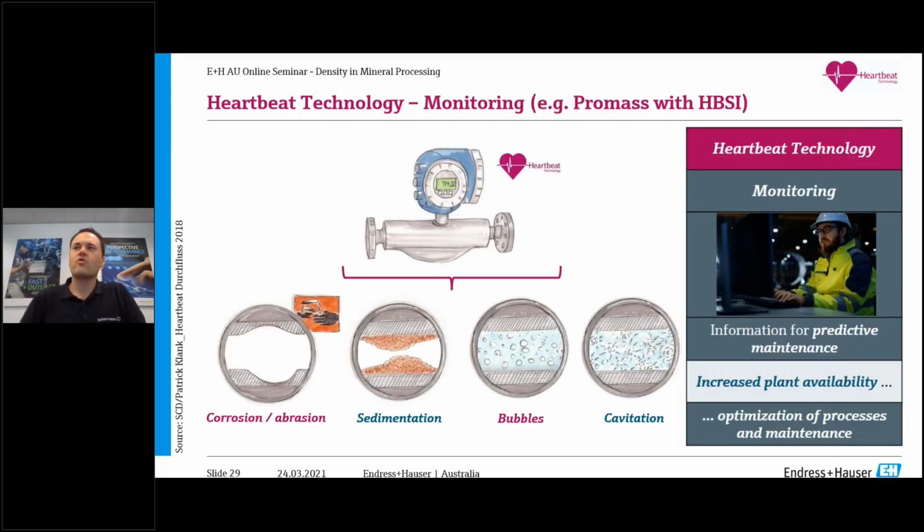We had some more questions also around, okay, so you have these Coriolis meters and there's a slurry application, but the question's always asked: the slurry will degrade the meter, won't it? How do we know that there's going to be no holes in the meter, or that the performance or the accuracy isn't decreased because of this abrasion?